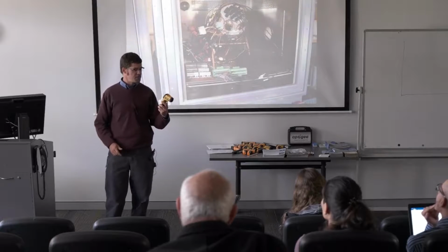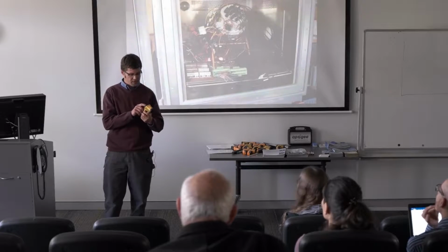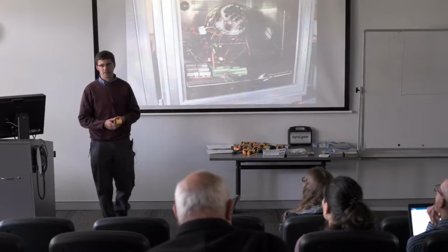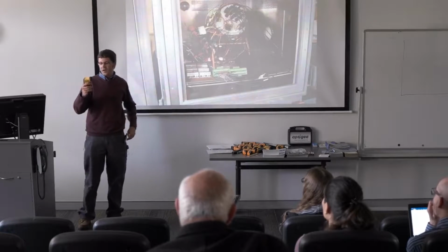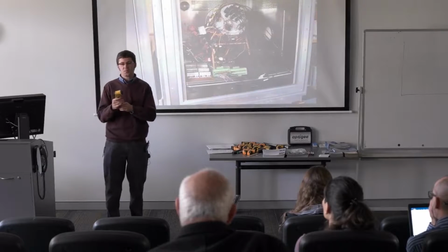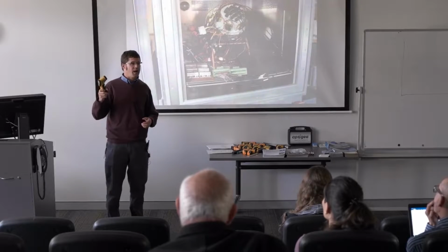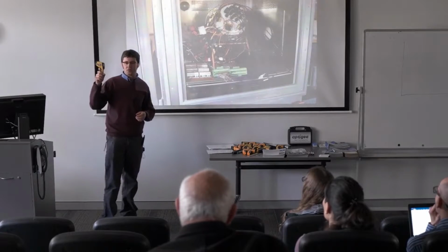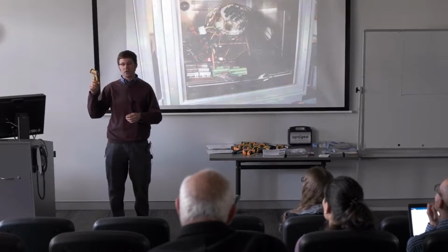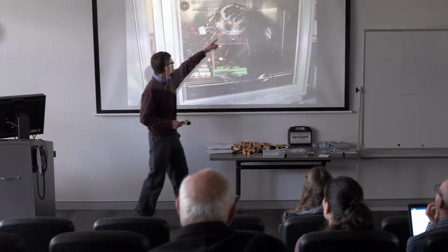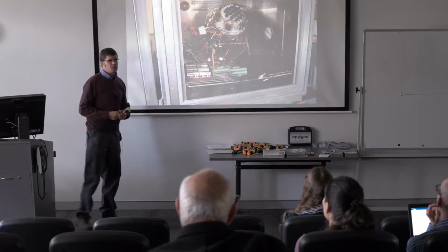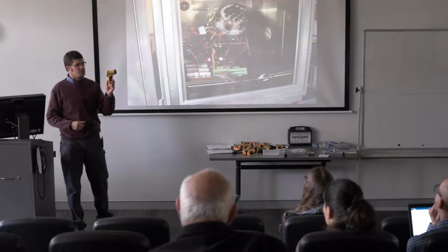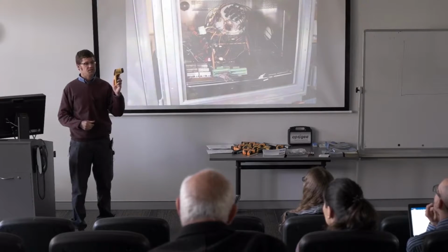So I just measured the temperature of the floor as 71 Fahrenheit, or if we convert it to Celsius, about 22 Celsius. Right? These are fine, especially for demonstration purposes or just spot checks where high accuracy isn't required. But the main difference between something like this that you can buy at the hardware store for a few dollars and something like this that we manufacture at Apogee Instruments is really the calibration. So something like this, the accuracy is probably 1 to 2 Celsius.